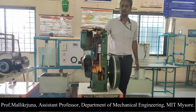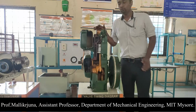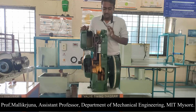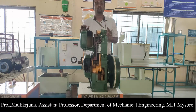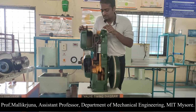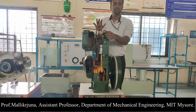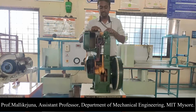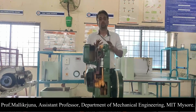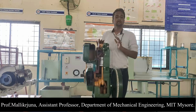Okay, now here we are with the valve timing diagram experimental setup. Actually, by looking into the cross section of the engine, we can say this is a 4-stroke diesel engine cross section. Why have I identified this? This is the fuel injector, so because of that I can say this is the diesel engine, and I am seeing the valves over here, so because of that I can say this is the 4-stroke engine. So finally this is the cross section of a 4-stroke diesel engine.